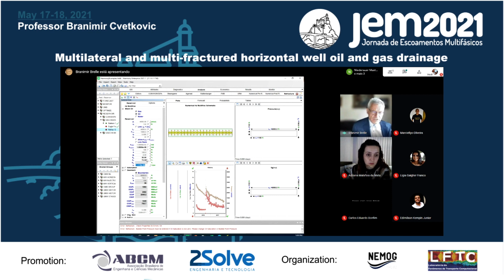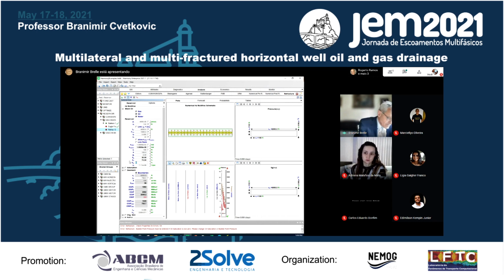Saturation of oil I have to change, because it has always to calculate that I'm combining gas and oil. So SO plus SG, SW, because I don't have any water here, so it is equal to 1. So it's always 100% here. And then I can include water. If I include water, I have to put, let's say, 5% water. Okay. So then it is going to say I have 25% gas, 70% oil, and I have 5% water. And then I have compressibility of fluid. It is okay.